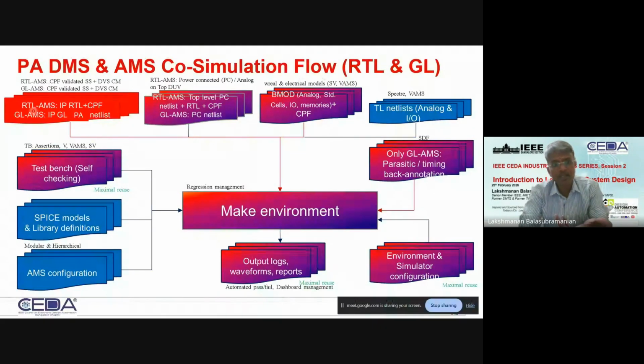And for RTL, you will use a detailed design CPF or UPF. And then at gate level, when you go to power-connected gate level, you won't use any power intent, because the power connection and full implementation, including retention, isolation, level shifting, power switch, etc., are already there in the netlist, right? Including their gate-level abstraction. So this is how the system looks.